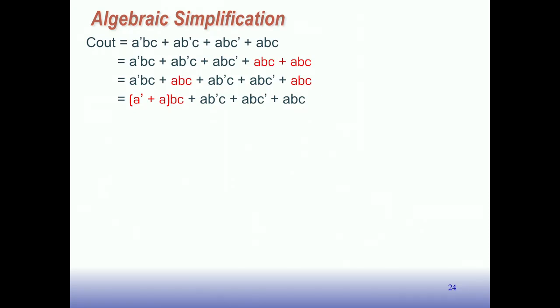Because either that's a 1 or that's a 1 in all cases. So we can replace that by 1. And so what we've done is reduced those 2 terms down to BC. It turns out really what this is just an application of one of those simplification theorems, but I spelled it out for you here without directly applying the theorem so you can see exactly how it works.